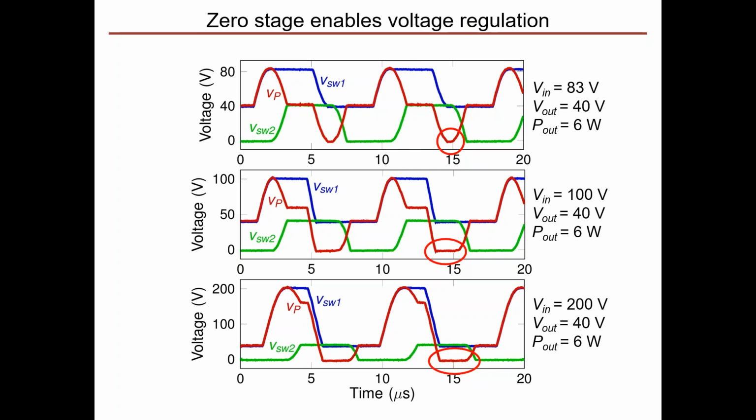What role will these topologies play in the integration of EVs in different forms and different applications with renewable penetrated grid integrated systems? What I can say about this is that this is going to shine more in the high voltage, low power applications. In terms of the bulk of the power transfer for an EV, I don't think this is the best bet. I think a magnetic converter is probably better. But in situations for each of those applications where the voltage is high and the power is low, I think this could be a fit.